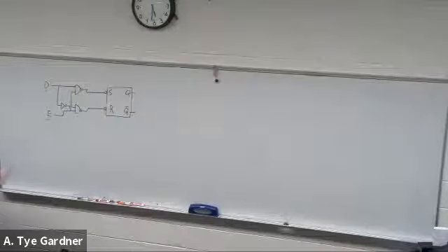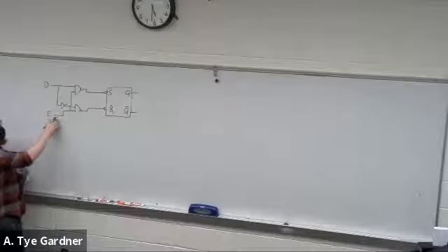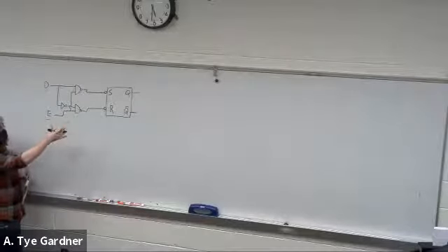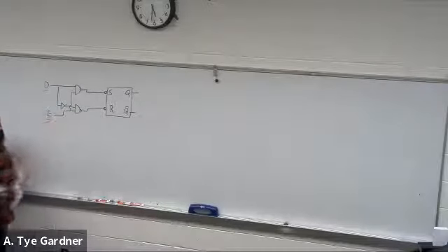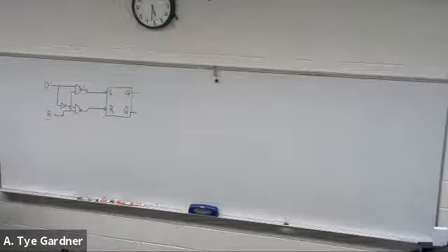Right, because D is feeding into this. So enable is just turning this into a pass-through. This is creating a gate, is what we call this. And saying that if it's enabled, then I can start setting or resetting. Otherwise, data can flip all around and do whatever it wants.